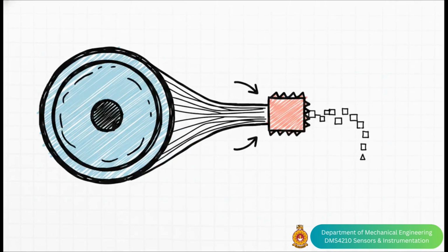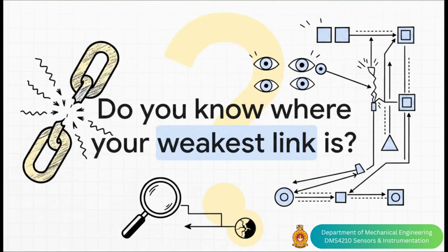Let's look at this in the real world. Say a system architect pairs a highly expensive, top-tier accuracy sensor at stage 1 with a cheap, low-resolution analog-to-digital converter during stage 2. The result? Well, the overall system accuracy will be strictly limited by that low-resolution converter. It completely negates the high-accuracy sensor. It's a total waste of the sensor's capabilities. System architects absolutely must ensure that the performance specifications of all components are mutually consistent and perfectly matched for the intended application.